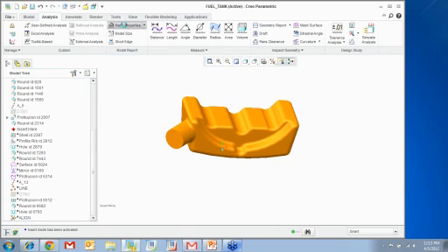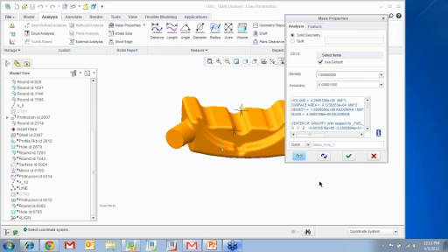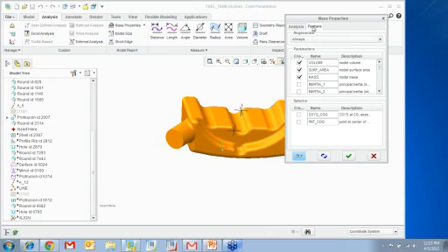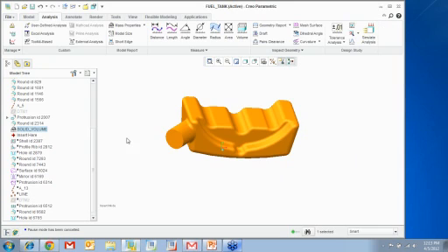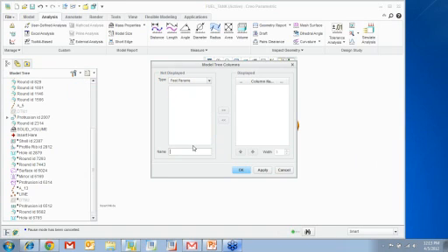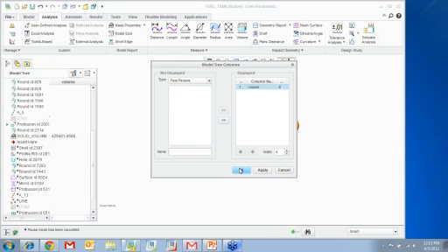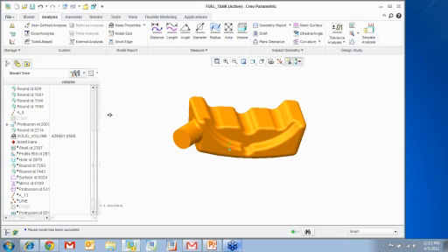So I go ahead and run a mass property analysis. Now in the mass property analysis, I'm going to save it as a feature, and I call it solid volume. Right? And then you can see that it will automatically create a volume parameter for you. So I go ahead and add it. So how do I find out what the value of the volume is? I can go to 3 columns, feature parameters, and type in volume. So here I have the current volume of the fuel tank.